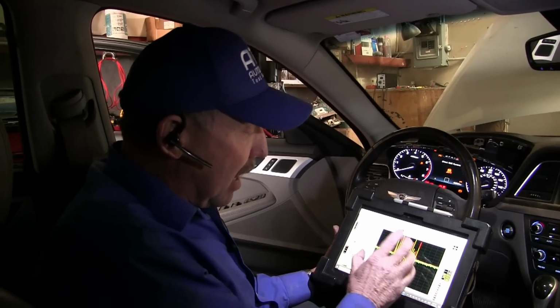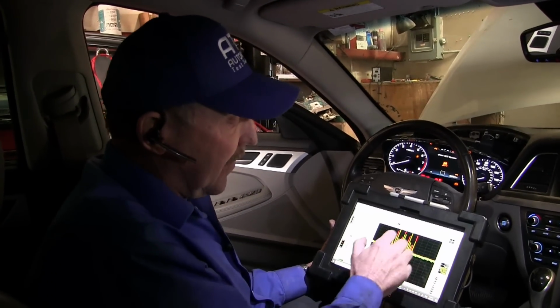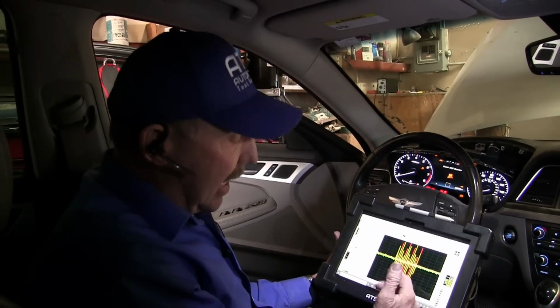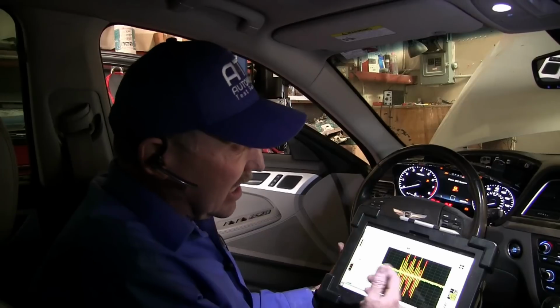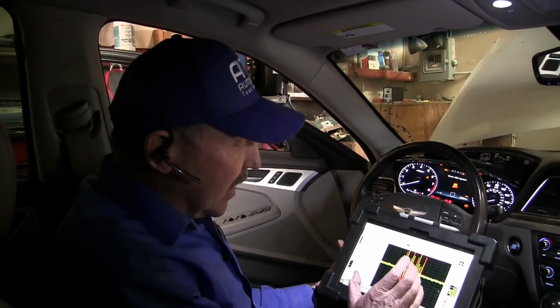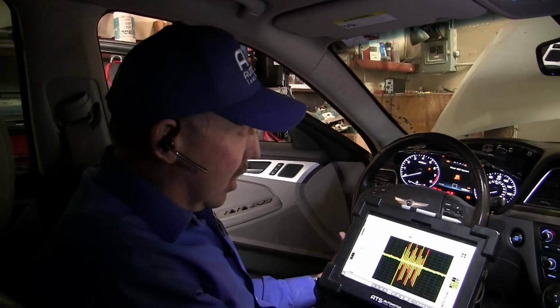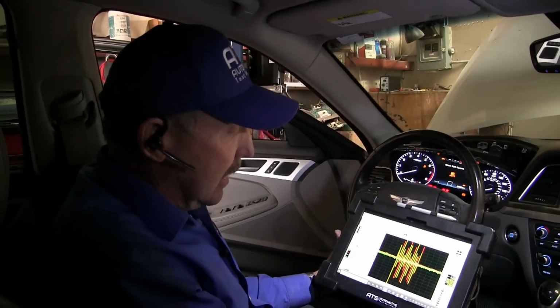This looks to me like one of the modules has failed, and the module's transceiver has a failure, and it's causing this data problem. And you can't transmit data when we don't make good zeros and ones, or good voltage high and voltage low, which is a Boolean code, so we can send data across the wire medium. So this is definitely a problem. So we have a module bad on the car, so now we're going to need to find it.